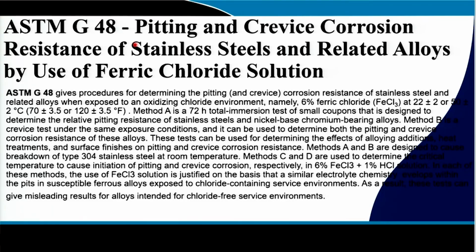So, there, if you go on estimating the pitting corrosion behavior by the typical standard immersion testing technique, you basically immerse the component in the solution and try to find out the surface condition at regular intervals, and measure the area fraction of the pits which formed on the surface. So, this is called standard coupon testing.